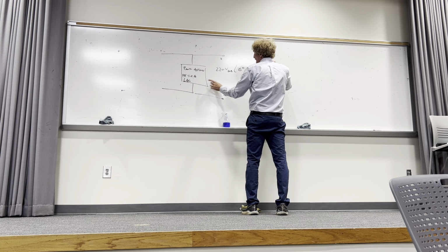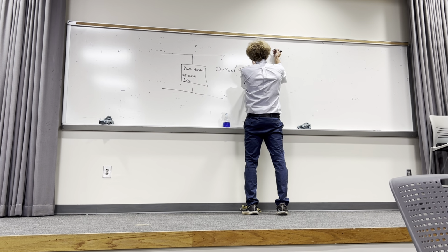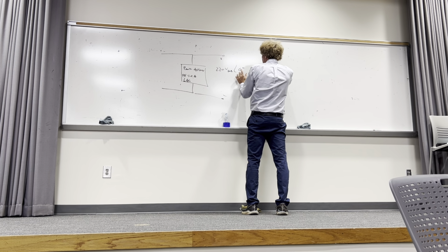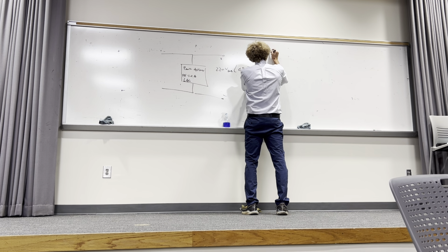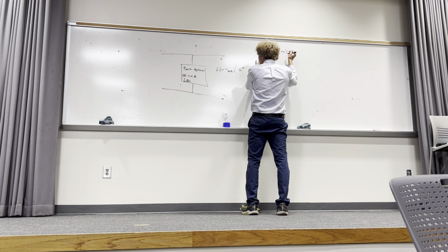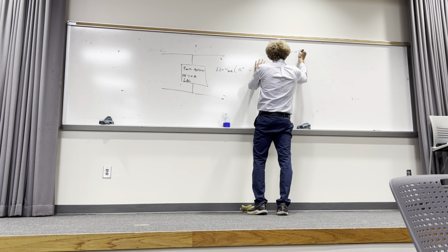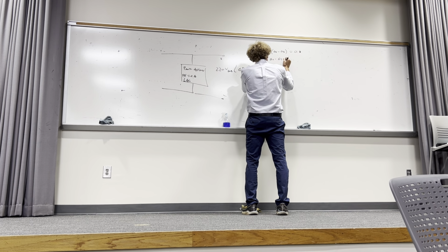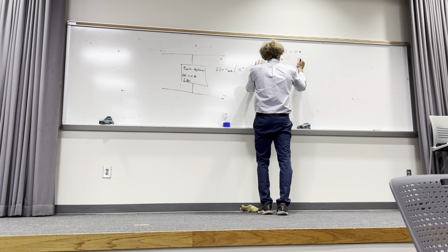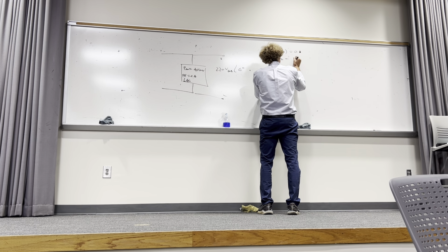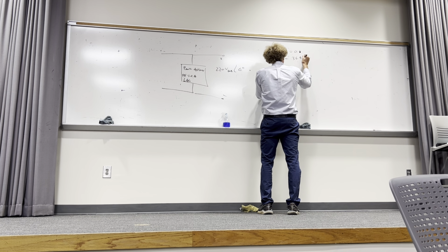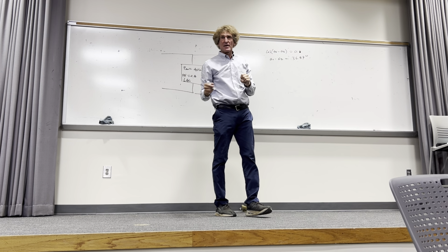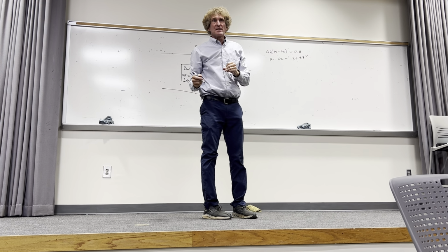So when I take a look at the angle associated with that power factor, and I've made this angle 0 on purpose, I know the cosine of theta v minus theta I is going to be 0.8. So that means theta v minus theta I would be the inverse cosine of that, right? And is that 36.87 degrees, or is my memory failing? Yes. Is that right? We did this last time, I think.